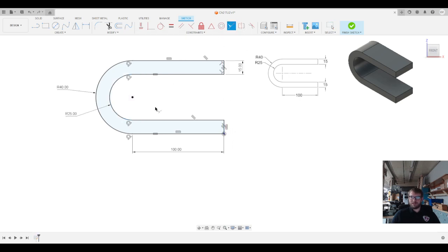So you'll get more into constraints in the next chapter, but that's just a little bit about constraints. You can get everything to snap in so it's black, it's all even. Or I think I already said this, but you can make that equal to that, and that snaps them all in place. So there's different ways to fully constrain your shapes, but it's good to practice getting them all fully constrained.